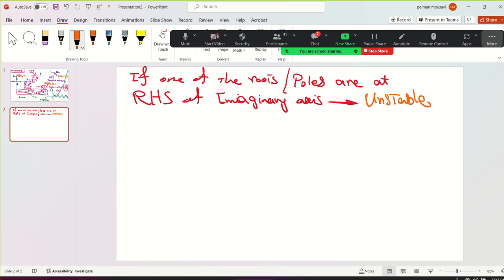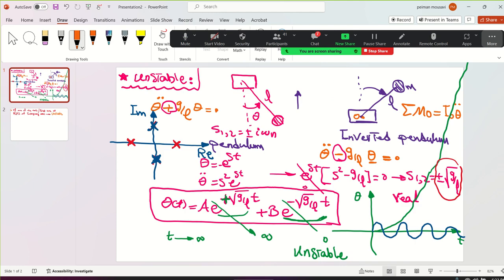Unstable. Now you are learning the fundamentals of control. We know that if you have a pair of pure imaginary poles or roots, your system is marginally stable, meaning physically your system is going to oscillate forever. But when you see this, at least one, because you're going to have a third order system, fourth order system, 10th order system, meaning 10 poles, 10 roots.